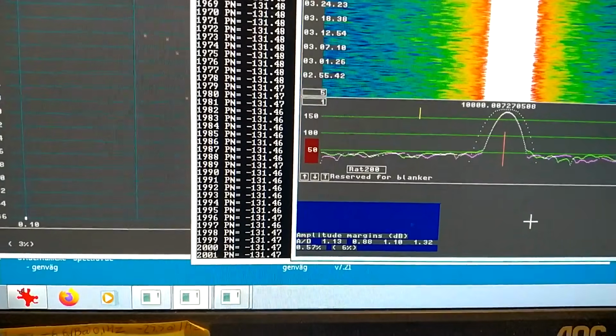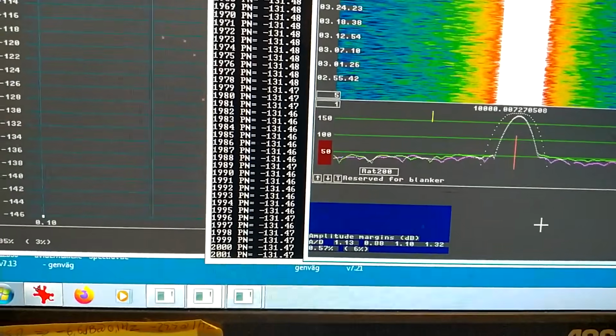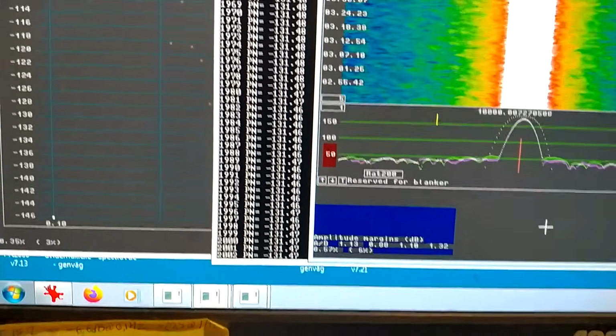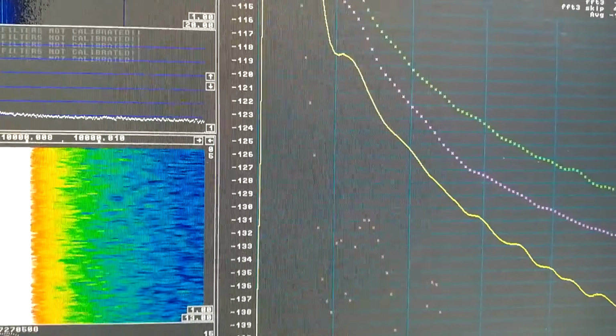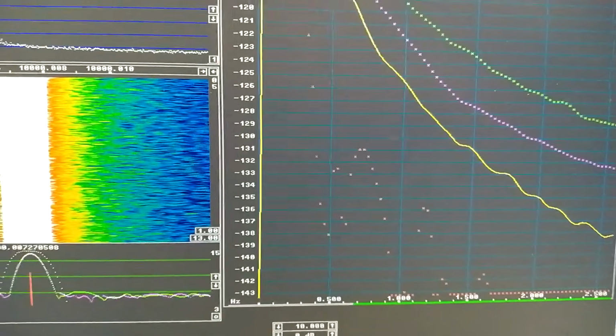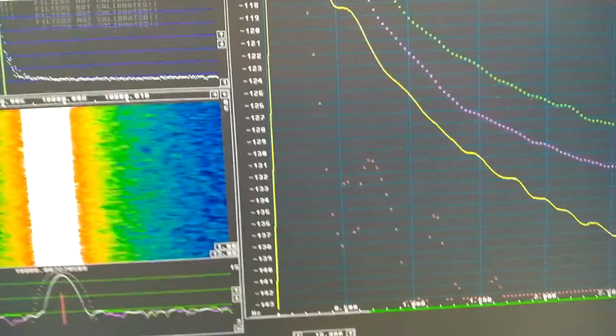I have removed the amplitude limiter with 2 crossed diodes and replaced it with a gain control using a FET. This has improved the average noise by about 1 decibel. And when I look here, Linrad tells me the noise at 1 Hertz offset is -125.5 dBc per Hertz.